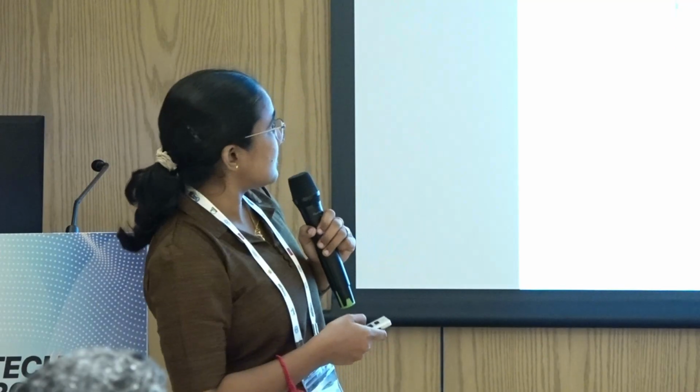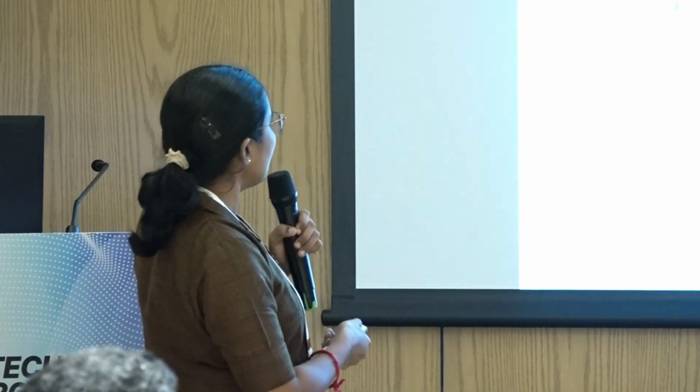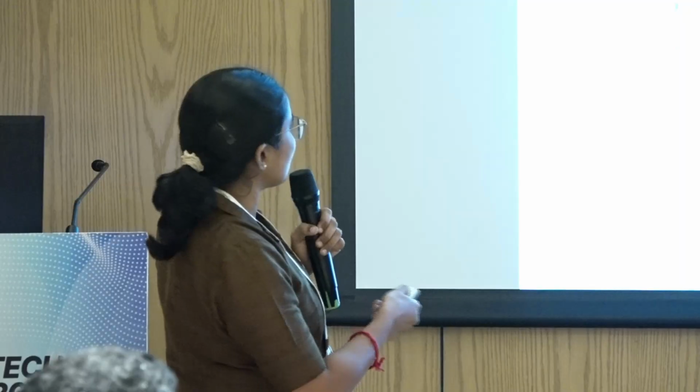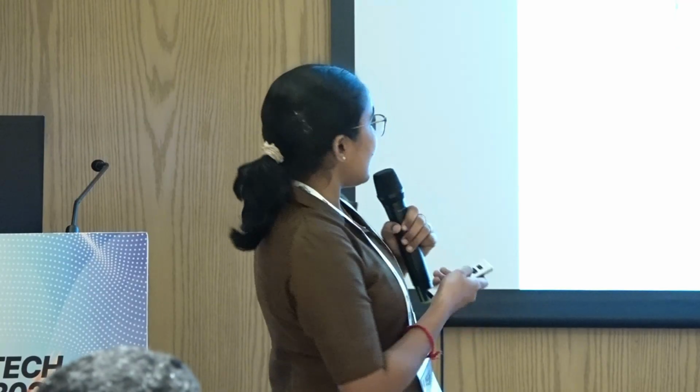And the CBR analysis we have also done, with resilient modulus testing using cyclic CBR testing. In this also we observed the CBR reached up to 15 to 16%, which was not equivalent to that of xanthan gum, but it has given enough strength to satisfy the IRC code requirements of 5% or above, or 10% or above CBR, to be used as a subgrade. And resilient modulus was almost 70 to 80 MPa. And when this was subjected to durability analysis, it passed through all 12 cycles.